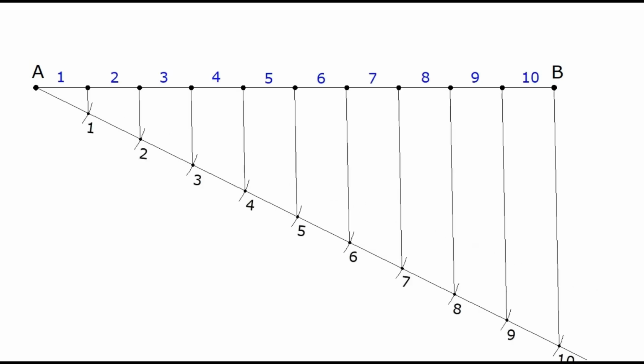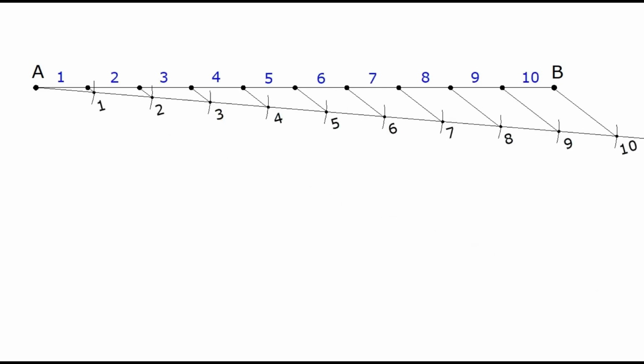It will be good if the line is drawn with an angle between 15 degrees to 25 degrees. If the angle is more, the entire drawing may occupy more space in the drawing sheet. If the angle is very less, the drawing will be very congested.